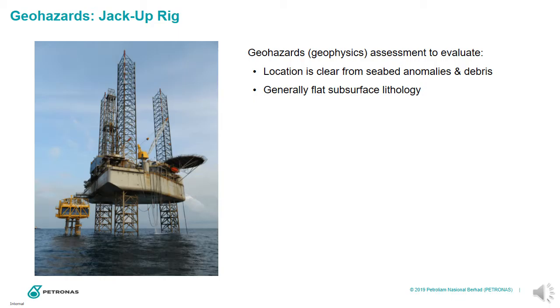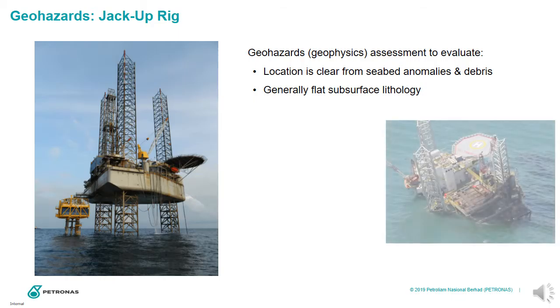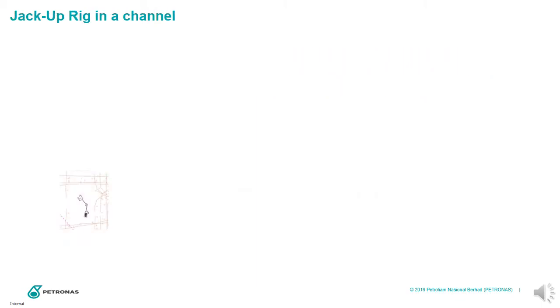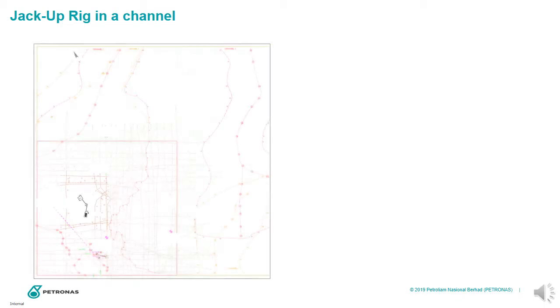The subsurface lithology should also be generally flat to prevent instability, which may result in damage to the legs, the structure itself, or even the loss of the rig. Ideally, there shouldn't be any challenging subsurface geology to contend with, but unfortunately, this is not usually the case. There are often times when the situation calls for siting a rig on top of a channel.